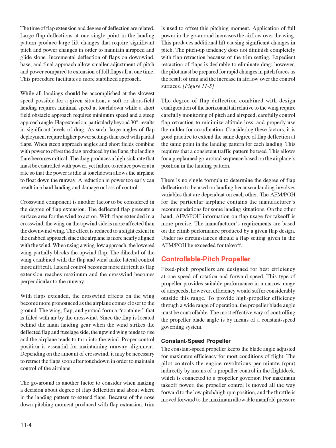There is no single formula to determine the degree of flap deflection to be used on landing because a landing involves variables that are dependent on each other. The AFM/POH for the particular airplane contains the manufacturer's recommendations for some landing situations. On the other hand, AFM/POH information on flap usage for takeoff is more precise. The manufacturer's requirements are based on the climb performance produced by a given flap design. Under no circumstances should a flap setting given in the AFM/POH be exceeded for takeoff.